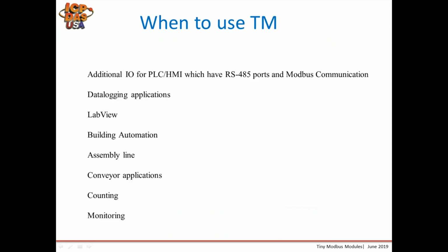Next slide. Okay, when to use the TM module. The TM module is great for PLC and HMI applications where Modbus communication is an available option. The PLC must have an RS-485 port, but since Modbus is a very common protocol, our modules are made to connect easily to third-party PLCs, HMIs, and SCADA systems to make it easy to use and easy to add.